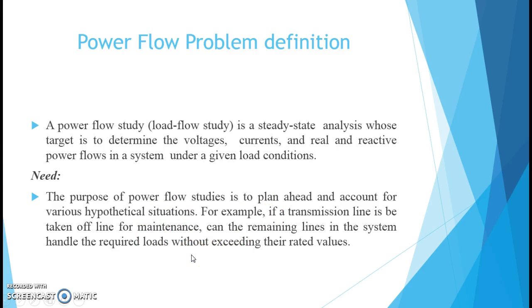For that I need power flow analysis. By doing it, I can know the power flow in various lines for a particular line outage condition. That is the main need of power flow analysis, to test the system for some unregulated condition, or you can say some hypothetical situation.